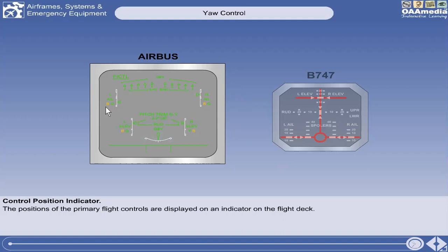As you can see here, the blue hydraulic system is amber in color, so there is a problem. Okay? Or inoperability in our blue hydraulic system, that is why it is amber in color. And this one, for the rudder, it is also an indication, so you can know the angle of deflection of the rudder, either in the right or left position, and also the elevator, the level of the angle of deflection of the elevators, and also the trim tabs, those are also shown there. Okay, so that is the indication regarding the flight controls.